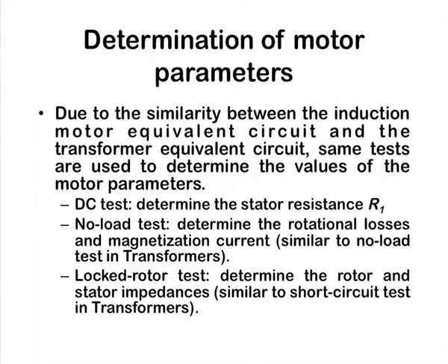Now, after going through the torque speed characteristics of induction motor, we will talk about the determination of motor parameters. Due to similarity between the induction motor and the transformer equivalent circuit, the same tests which are being used for transformer can be used to determine the motor parameters.